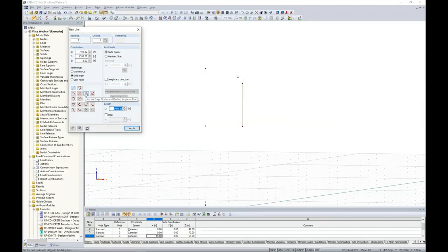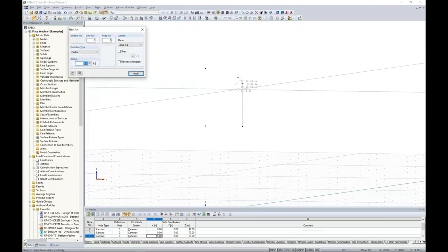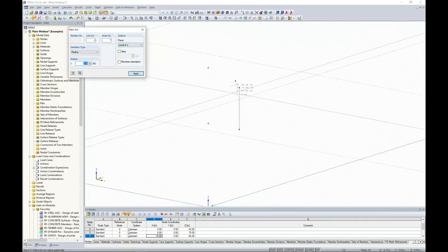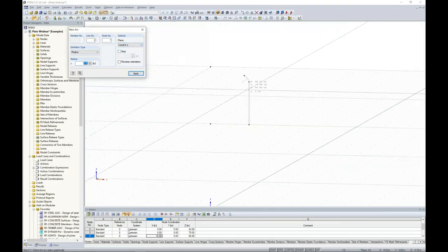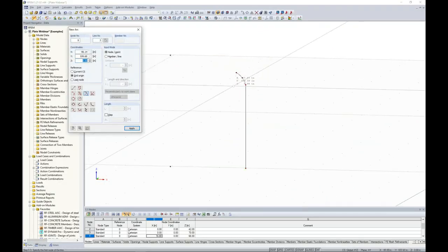So we have the ability here to define an arc, and I can select from one node to the next. Now, currently this is in the correct orientation here for defining my radius. But if we saw that the radius was being defined into the page here, all we need to do is just to adjust the plane, local, and Z. Then I can simply type on my keyboard the radius of 5 inches. I hit enter, and now we see a slightly curved line here.